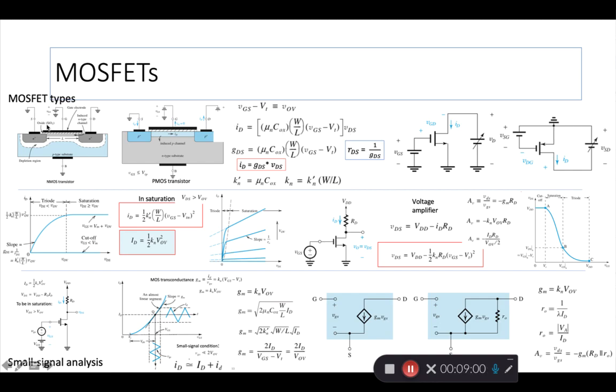It is related to the capacitance that's created here by applying just the gate to source voltage. So they always come together. And then there's a W by L, which is the width by length, and you see these factors quite a bit in the formulas in PMOS, NMOS. So I hope by now you have become familiar with them. If not, please, it's not too late, become familiar with them.